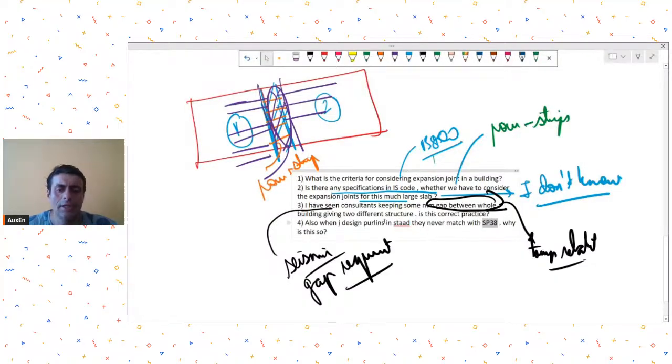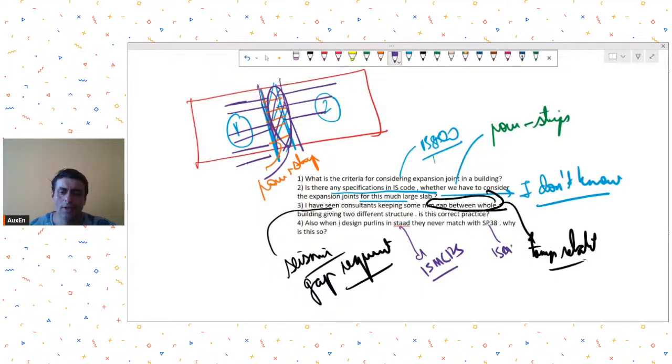That means, let's say for a 6 meter span, for 1.25 meter or 1.4 meter center-to-center spacing, if in STAAD, let's say ISMC 125 is passing, SP38 gives you ISMC 150. So generally it will give you more conservative sizes. Keep that in mind as well.